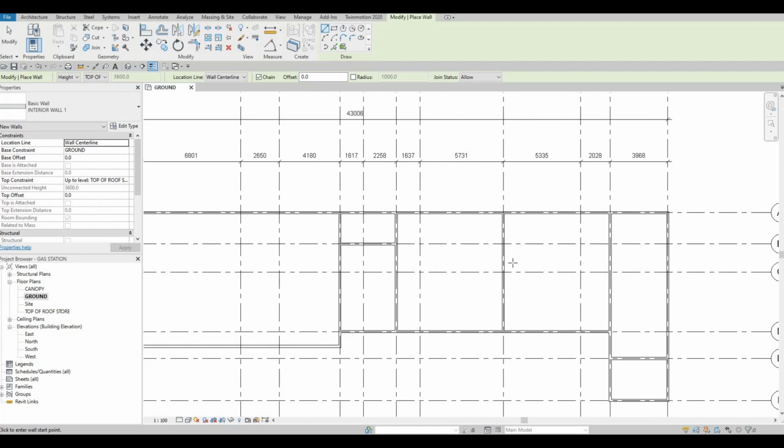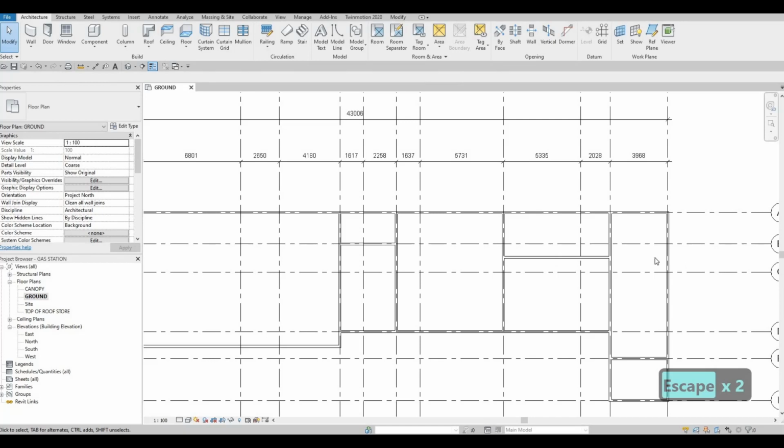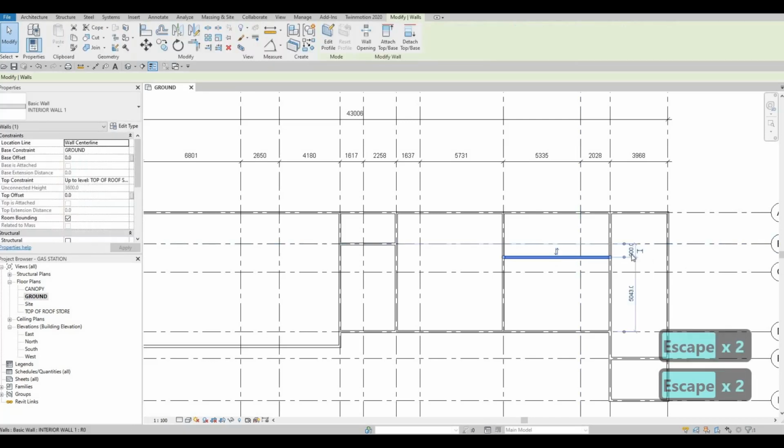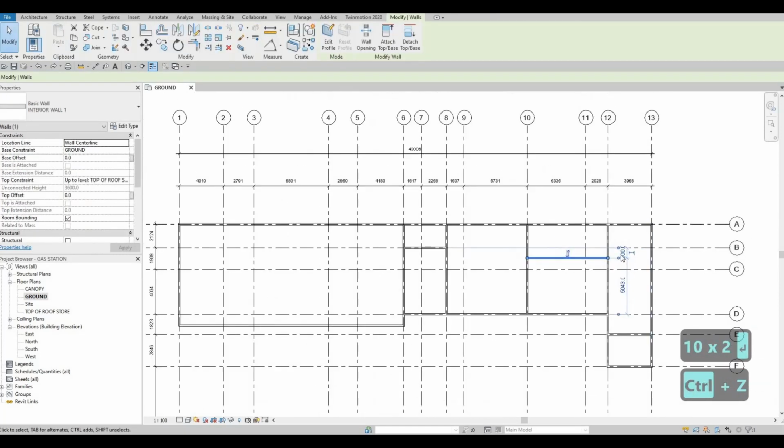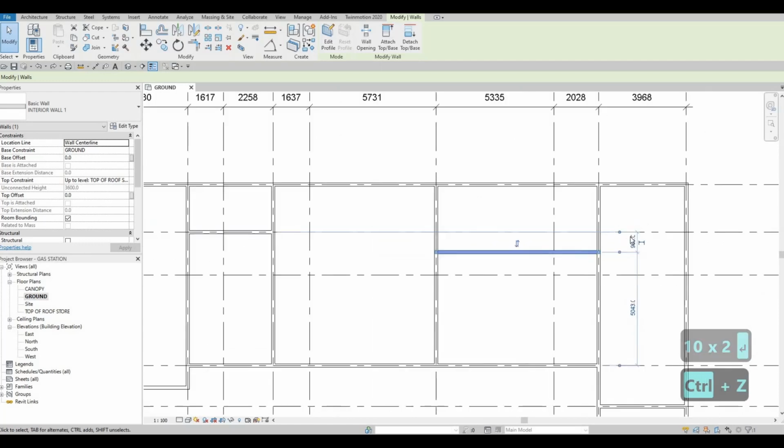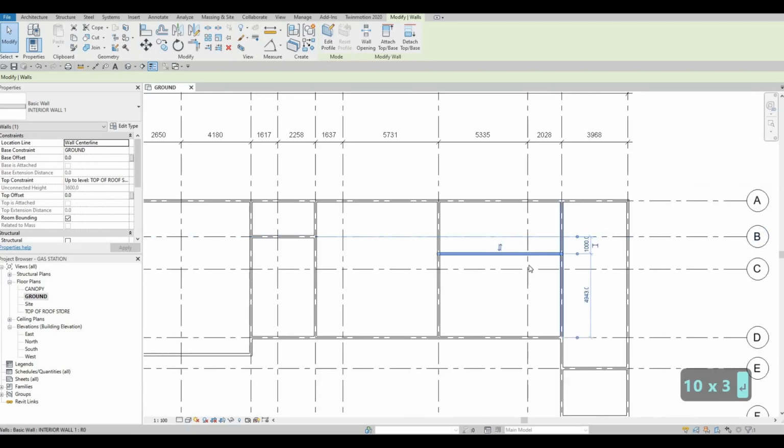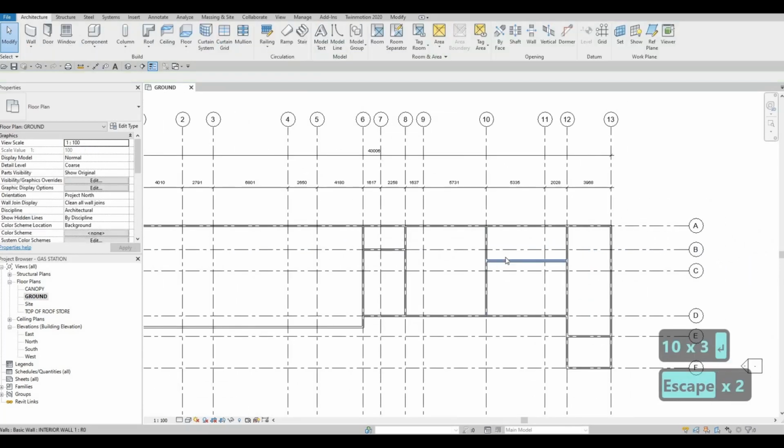We're going to add a line right here in the middle. So don't worry about the distance yet because we're going to figure it out. It will be just 1,000 away from that grid line, which is the B grid line. So I'm setting it up so that it will move from this grid line right there. So as you can see, the wall moves as well.